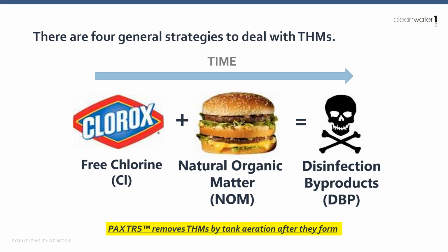And I've got a great example from one of my customers up on the coast in Oregon, who was working with us on a THM aeration system, but it was taking a long time to get funded. So they had some time to really look into different types of coagulants, and they did their homework. They did their jar testing, and they were able to more or less eliminate their problem with disinfection byproducts by switching coagulants.